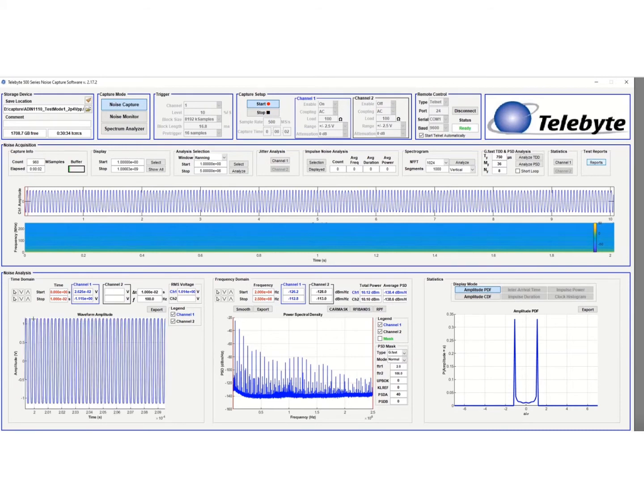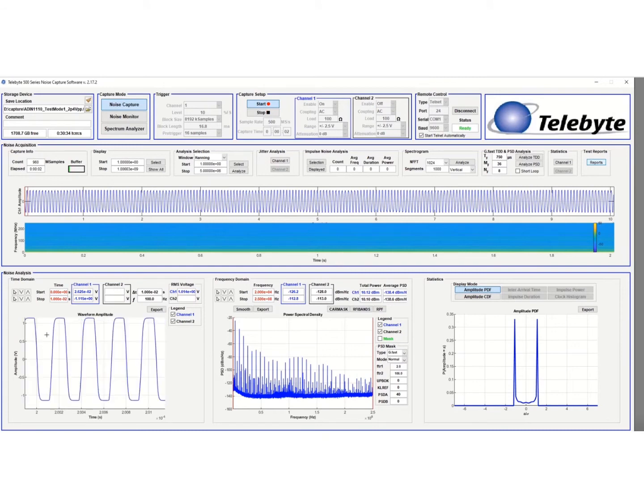By drawing a rectangle around the signal, you can see it looks like what we're expecting for a test mode 1 signal, +1 followed by a -1. So you can see the signal level here. But what we want to do in test mode is see what these transmitter output voltage level values are, as well as look at jitter and the clock frequency.